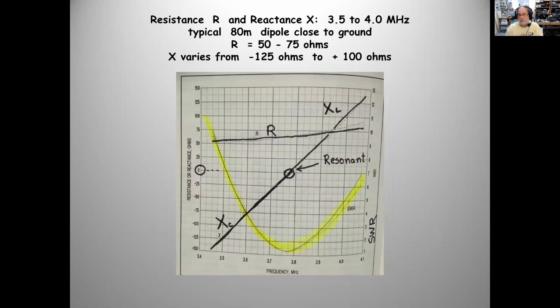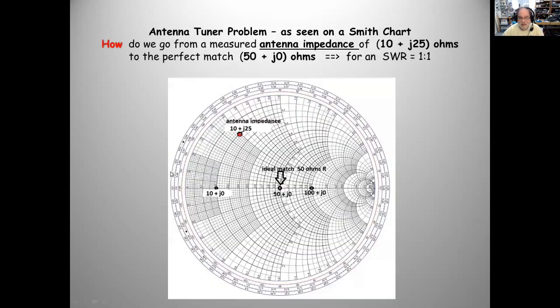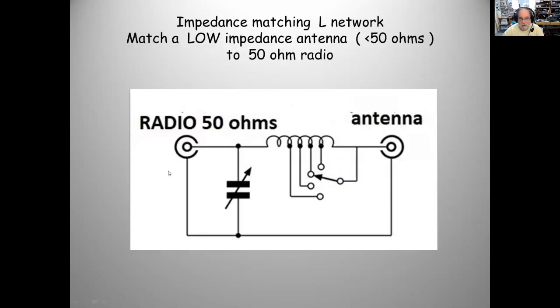So what's my antenna tuner actually doing? It's sort of protecting my radio from seeing the bad stuff. Does that make sense? How does it do that? Let me jump ahead a couple. It does it by introducing another reactance. So if my antenna is capacitive, I throw in some inductive reactance, and this acts as a combination of two to bring the resistance back to 50 ohms.